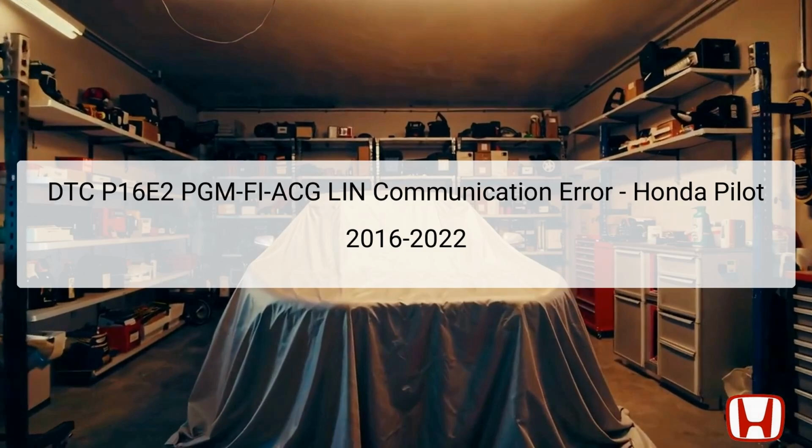The diagnostic trouble code DTC P16E2 indicates a PGM-FI-ACG LIN communication error in the Honda Pilot models from 2016 to 2022. The acronym PGM-FI stands for Programmed Fuel Injection, which is critical for ensuring the engine operates efficiently by controlling the fuel injection process. The ACG refers to the alternating current generator, commonly known as the alternator, which provides electrical power to the vehicle systems and recharges the battery.